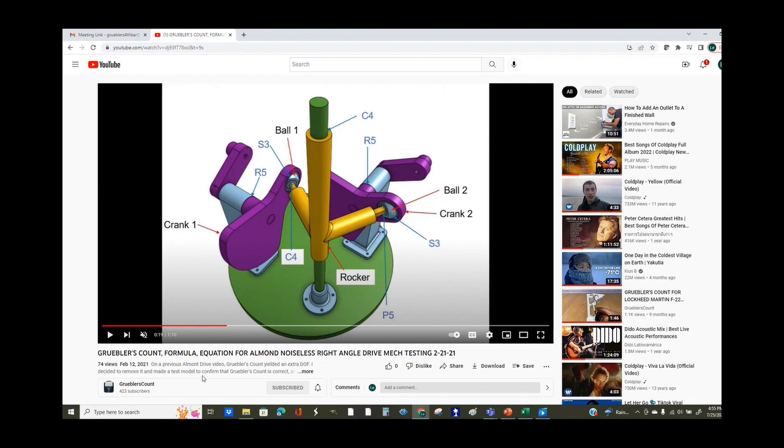You see that? One thing that's nice about Gruebler's is that you don't have to worry about lining things up so perfectly, you know? You can use bolt hole tolerances and it works fine. One of the things that Brian and I worked on, we made Universal Studios' first animatronic hand. It was bigger than my hand. That's like a 6-foot figure. And I was using Gruebler's on all the joints in there, and I didn't GD&T anything. I just used bolt hole tolerance, and it went together fine, and it worked great.